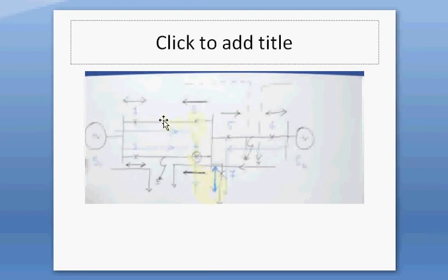How? Now let us assume there is a fault over here in between relay 1 and relay 2. In case of the upper feeder, the direction of current is from generator S1 to relay 1, and it will feed to the fault. Fine. Now in feeder 2, we will see that it is flowing from generator S1 to relay 3, then it will go to relay 4, then it will follow this path, and then it is flowing to relay 2, and now it will feed the fault.